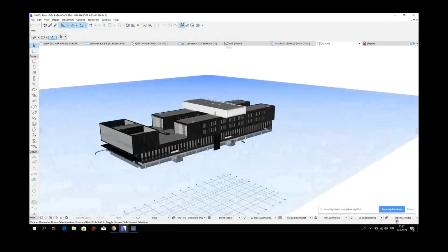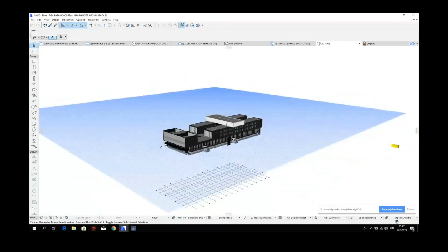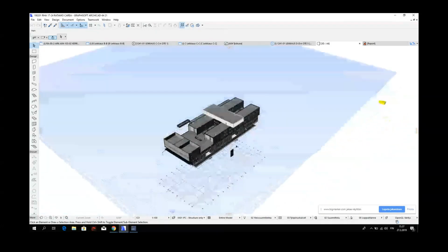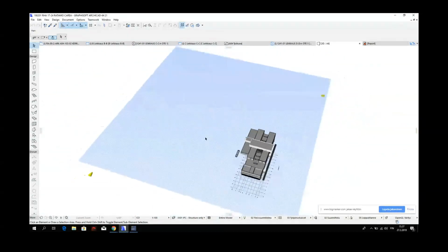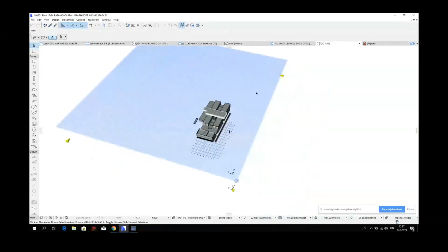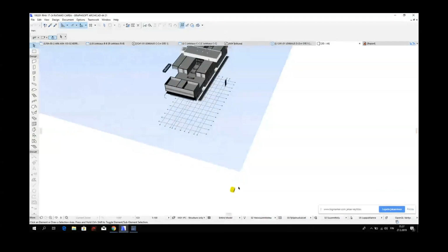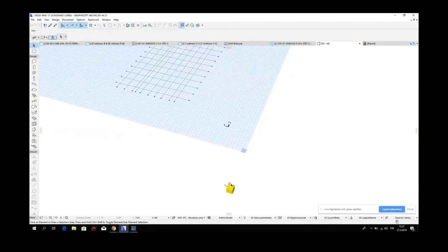And then we've also got in this project, and many of the projects that we work on, down here, these little reference marker points. Now this one down here is our project origin, so this is set at 000, and everything that us and the engineers and everyone else work off is based off that point, so that when we put all our models together, they should stitch seamlessly.